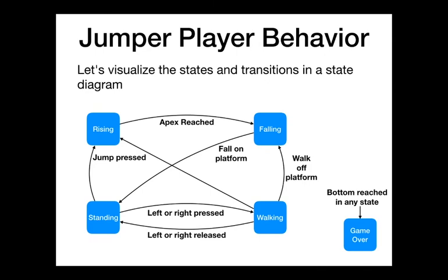So with all that, if we process all that, we can draw our state diagram. Highly recommended that you draw your state diagrams for your homeworks, for your lecture questions. If you come to office hours and you don't have a state diagram, it's probably the first thing I'm going to ask you to do. Draw out your state diagram, show me what your program is doing. To get your head around everything that you're designing, it is very useful to draw these state diagrams. When I was writing my solutions for calculator and microwave, I spent probably most of my time just with a pen and paper drawing state diagrams, drawing things out, making sure I have all the states I need, making sure all the transitions are good.